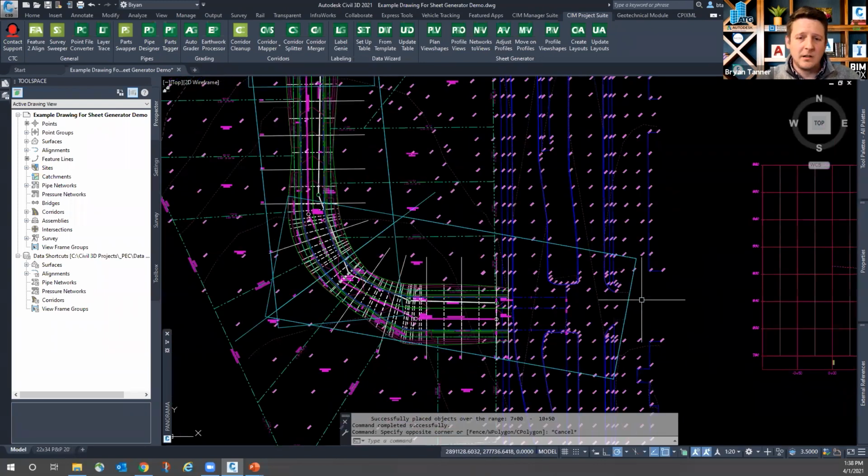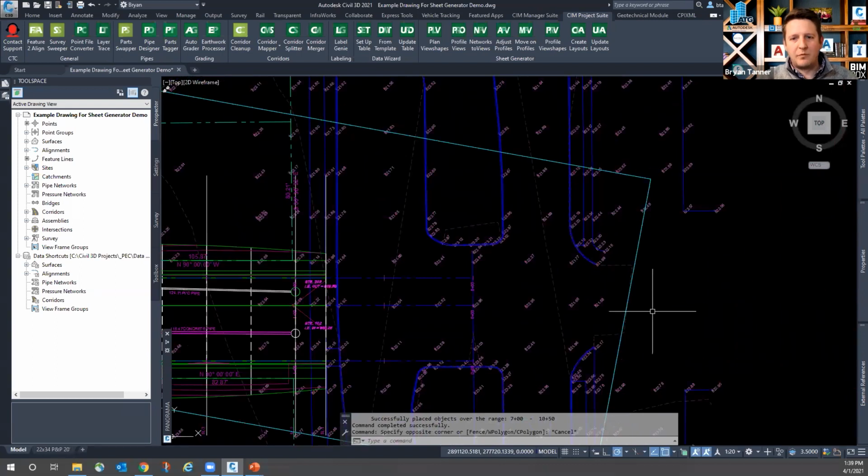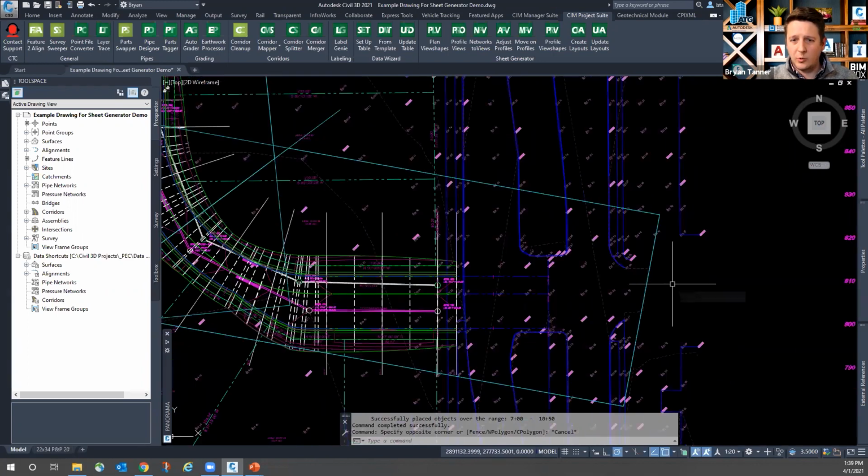Much like the Civil 3D Viewframe group, these are editable, but I can just use my regular old AutoCAD commands to edit these view shapes. I don't have to use those 3 limited grips of moving it or rotating it arbitrarily, because we don't really have good rotational controls or parametric constraints with it.